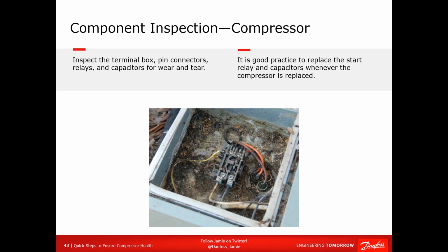Well, obviously, you're going to replace the start contactor relay. You're going to replace the capacitor. We also cut back and replaced it with new wiring. Okay, why? Because it's cheap insurance. You're putting something in there that's $1,000 or a couple $1,000, right? I have no idea if this stuff's going to work properly or what problems it could cause. So replace it along with the filter dryer as well.